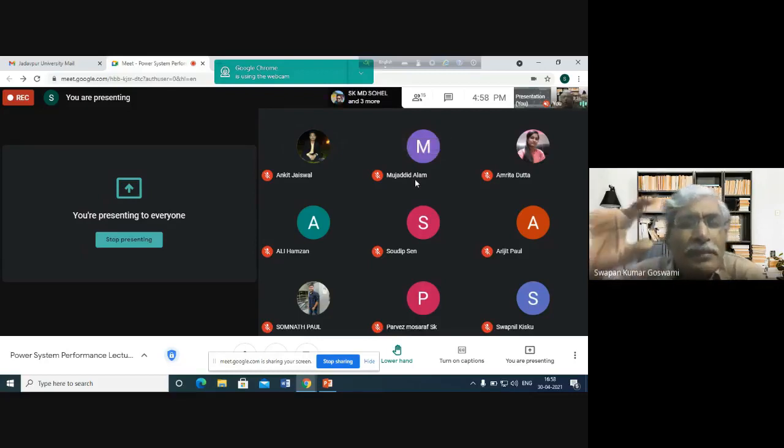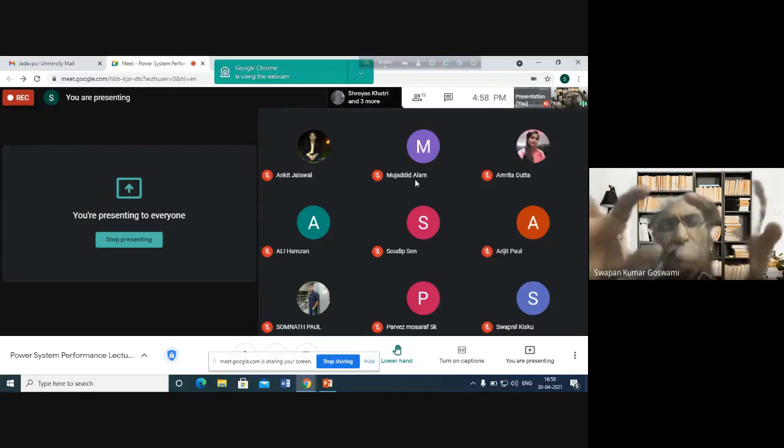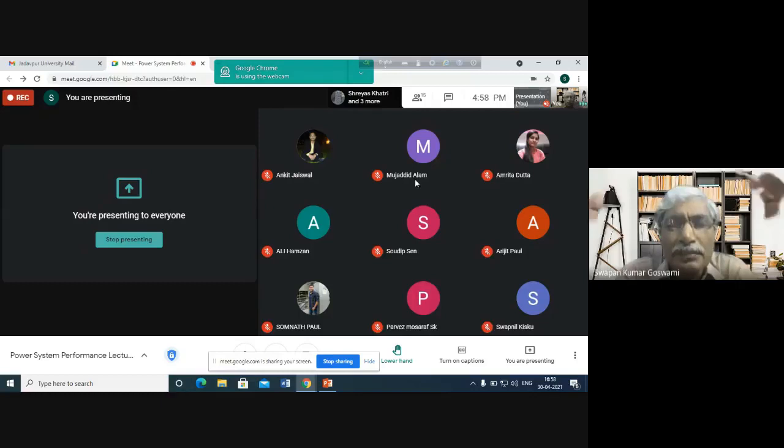So the effective surface area increases when you are using the bundle conductor. Say using the same volume of conductor as you have used in these two or three conductors in the bundle, if you use a single solid conductor, which is not separated, in that case the effective surface area will be smaller.